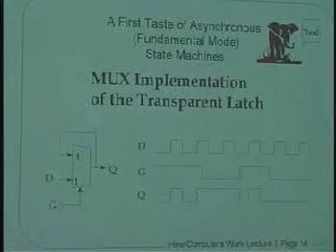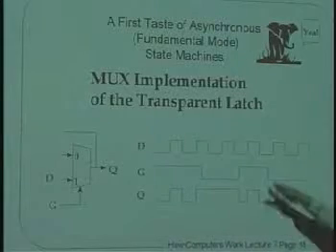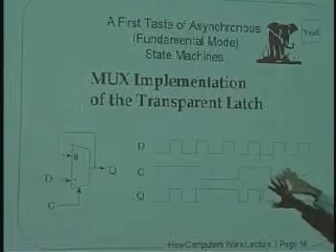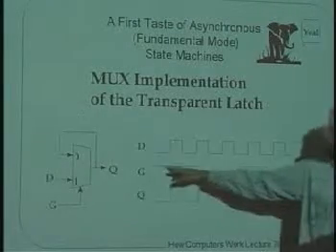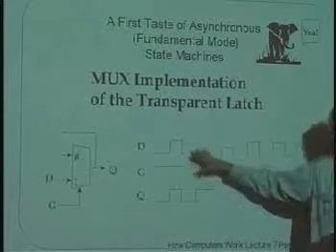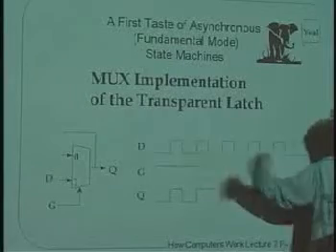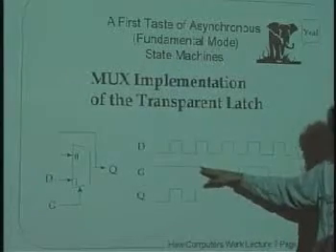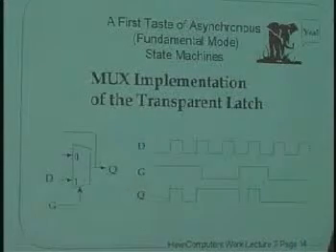Now, we don't have a register yet, okay? We don't have this flip-flop that's sensitive to edges. We're building something more primitive, which is this thing called a latch, a transparent latch. Now, why is it called a transparent latch? Because when the gate is high, it's like a window, and Q is a transparent copy through glass of D. Okay? However, it latches when G goes low and holds on to whatever the last value of Q was.